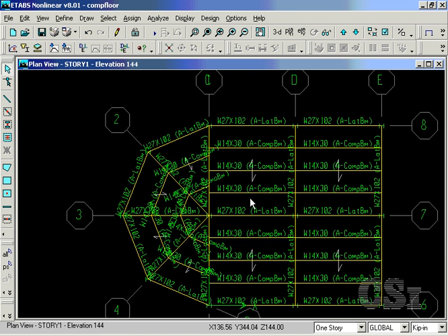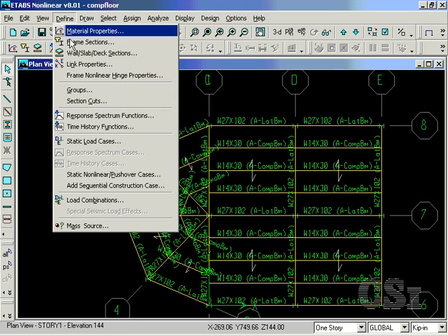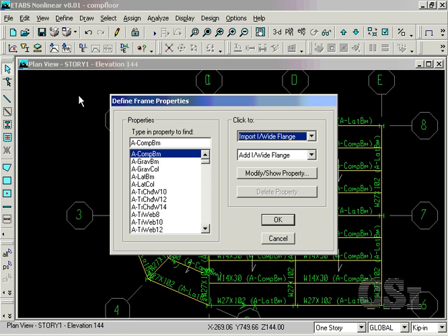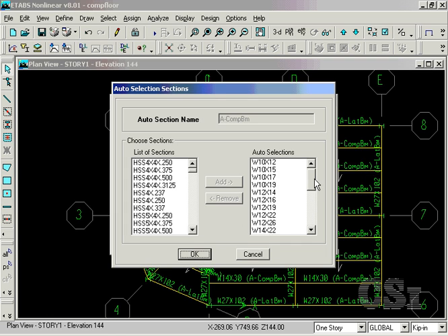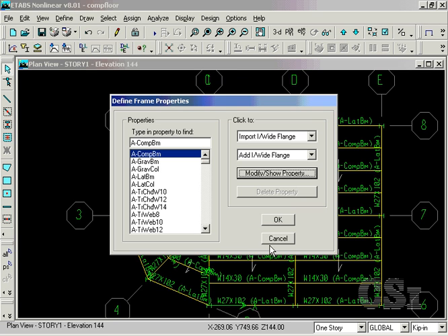The Auto-Select Composite Beam list is a predefined list of sections, which range in size from W10x12 to W27x84. The W14x30 initially selected is simply the median size member in this list.